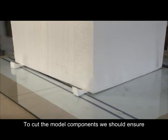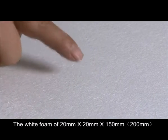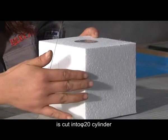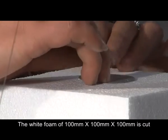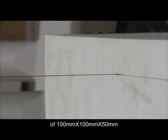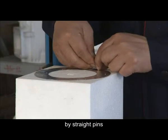To cut the model components, we should ensure the dryness and smoothness of the white foam. The white foam of 20 mm by 20 mm by 150 mm, 200 mm is cut into a cylinder of diameter 20. The white foam of 100 mm by 100 mm by 100 mm is cut into a circular truncated cylinder of 100 mm by 100 mm by 50 mm. The model should be fixed on the foam board by straight pins.